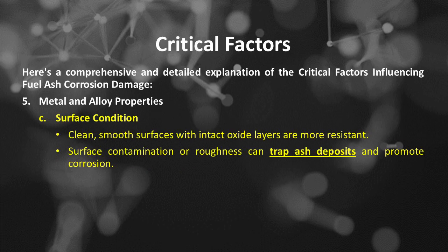Number C. Surface condition. Clean, smooth surfaces with intact oxide layers are more resistant. Surface contamination or roughness can trap ash deposits and promote corrosion.